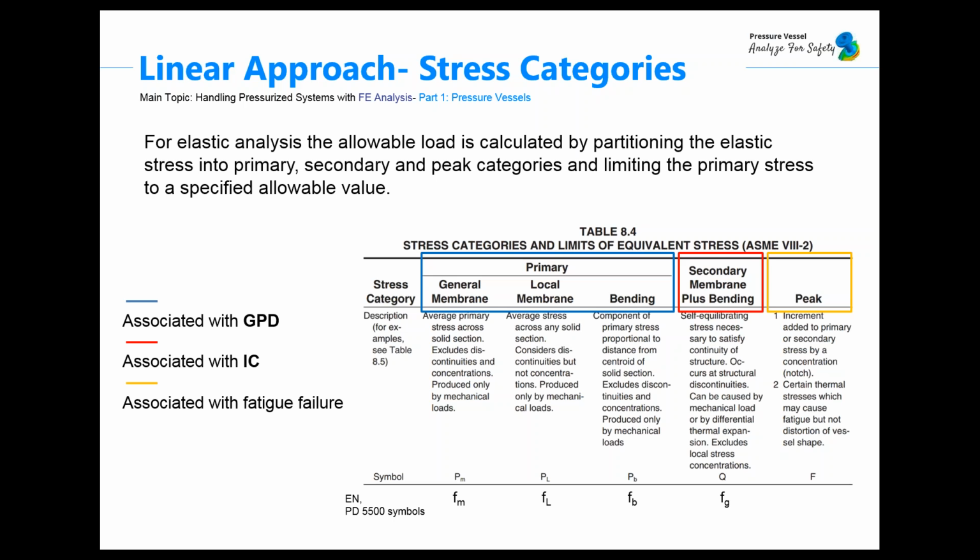which means that they are distributed within the structure so that no stress redistribution will occur as the result of yielding. An example of primary stress is the hoop stress within a pressure vessel induced by an inner pressure. By increasing the pressure, the stresses will increase until yielding. And there are 3 subcategories of primary stresses: general primary membrane stress, primary bending stresses, primary local membrane stresses.